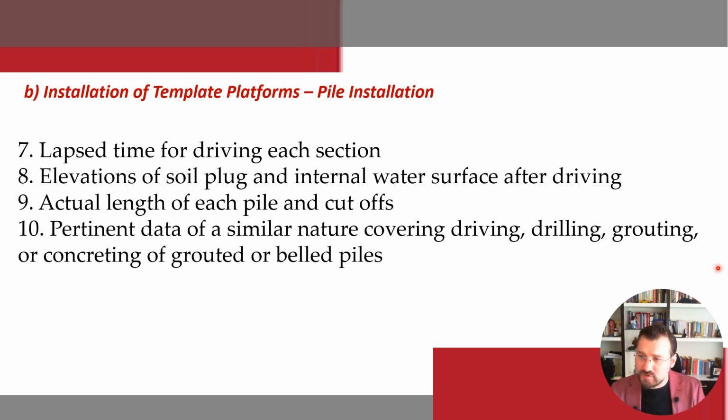Grouting. Another one is the grouting that we can talk about. The grouting following this one, after including the procedure of these 10 steps, is the next step that's performed after piling. Okay, after piling. So for this, there is a grout line for each leg and sleeve, which is connected to the bottom of the leg. And the cement slurry is pumped into this, and from the top, return water present in the annular space comes out through an outlet connection.